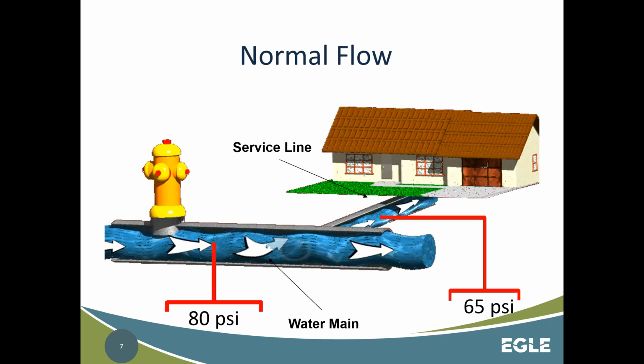All right, so one thing here that I want to point out, and we were unaware of for a while, is that here you can see the water's coming into the water main. It's 80 PSI. And the reason that's at 80 PSI is because the maximum residential pressure going in is supposed to be 80 PSI or lower. Just FYI, that's the maximum residential pressure according to plumbing code from 2016. So as you can see, the main's at 80 PSI. Here, it's going in at 65 PSI.